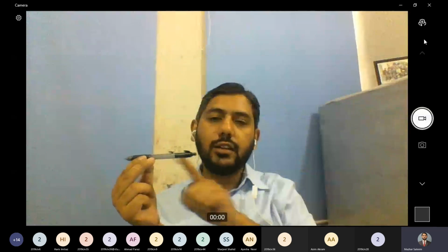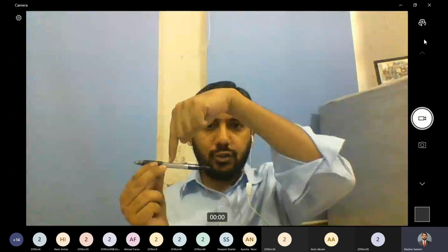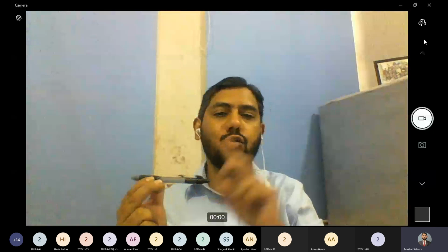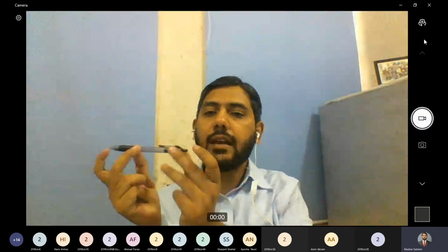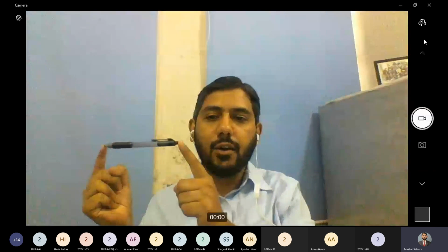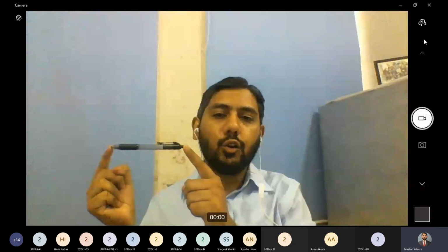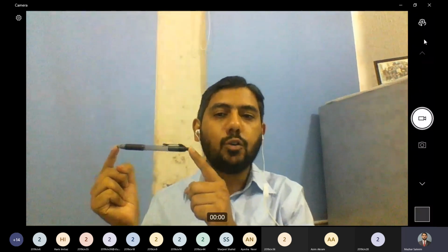If the beam is horizontal, then the transverse load in this case will be vertical, and this load is termed as transverse load. As a result of this load, shear force and bending moment, these two internal forces, are developed in the member. If we have the same horizontal member, but I apply axial compression on that, meaning I try to compress the member from both ends, this type of load is termed axial compression, and the behavior under this type of load will not be beam-like. It will be more like a column.